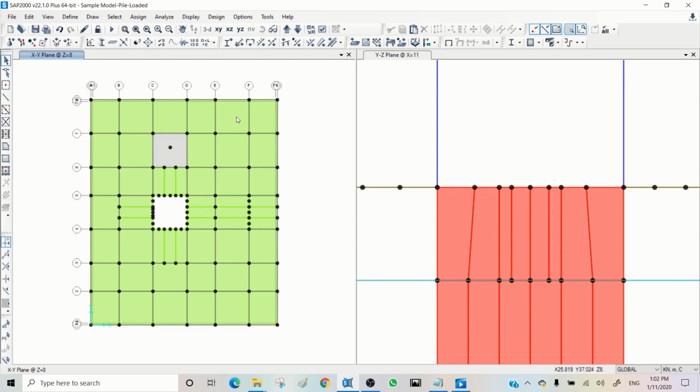You can subdivide these slabs to at least 2 by 2 or 3 by 3 to make it more reasonable. Don't go for very large number. It really back to the level of accuracy you need to see here in your frame. But minimum 2 connections are a reasonable option for you to connect this beam and the shell together. So what we can do here, it's up to us. Either subdivide this frame to 2 points and then automatic mesh the shell to that. We can do both here.